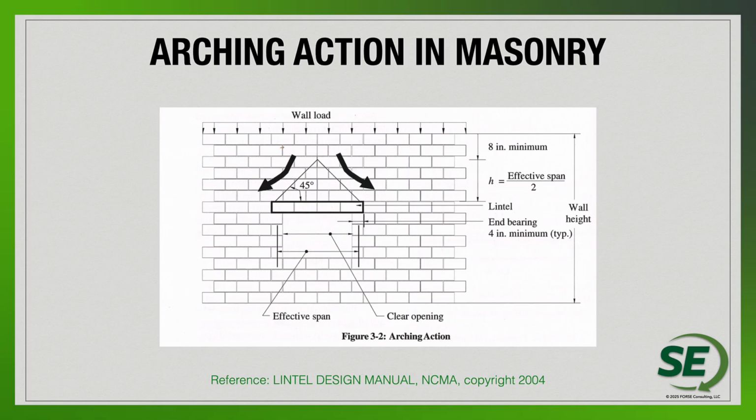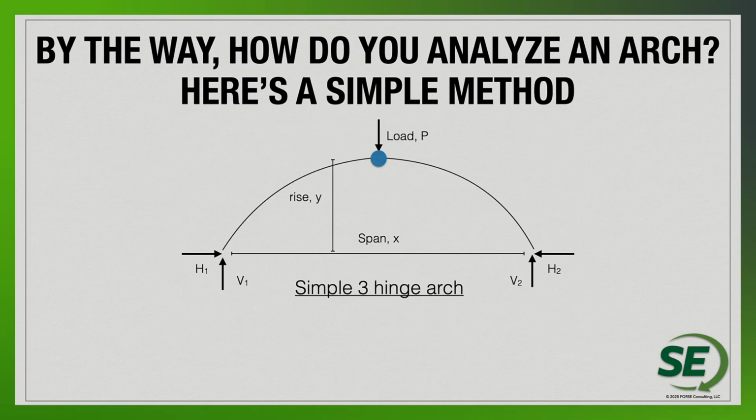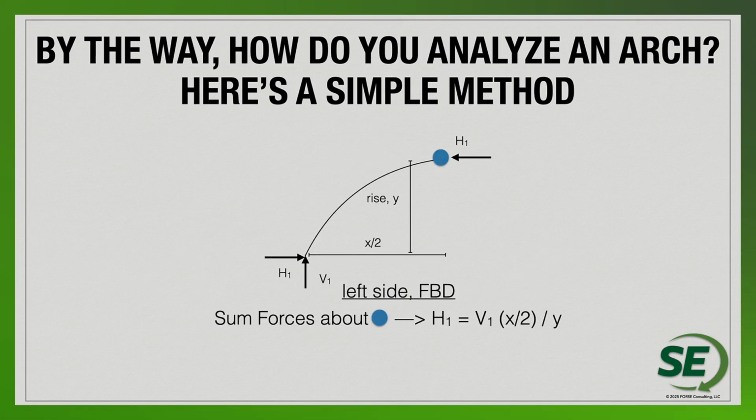but let's just start with some of the basics of what an arch looks like, what some of the different forces would be with an arch. So if I just took a very simple arch and we looked at this 3-hinge arch, if we just put a load at the center, we know that that force is not just going to be a vertical force at the supports. When we look at a free body diagram of half of the arch, we know that we have a vertical component and a horizontal component that we have to resolve. So there's going to be some thrust loads.